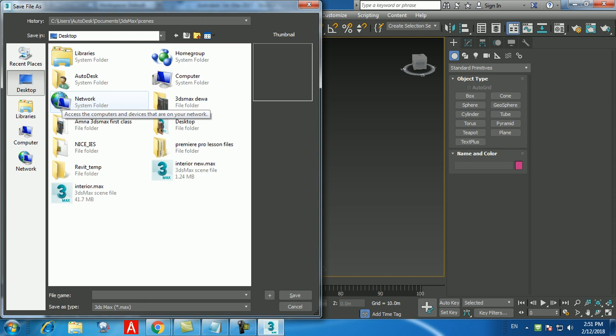Okay, my question is, if the guy has been working more than 10 years? Normally AutoCAD is more famous for keyboard shortcuts. You can do anything with shortcuts. Revit doesn't have shortcuts. In AutoCAD, every time you press spacebar or enter to finish the command. Here, if you press spacebar or enter, it will close the command itself. Totally opposite. So that is the reason you do the plan in AutoCAD, you bring it to Revit, you make it a BIM, which is a Revit object.